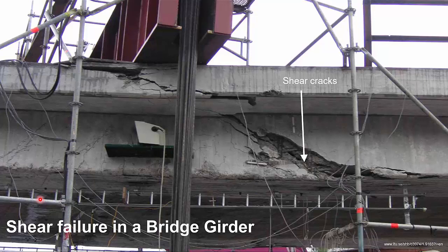The typical characteristic of a shear failure is large diagonal cracks, as you can see here. The diagonal cracks extend from the tension region up to the compression region, and the shear failure is governed by both the tensile strength and the compressive strength of the concrete. That is why shear failures are very abrupt and catastrophic, and we don't want structures to fail in a catastrophic nature like this one.